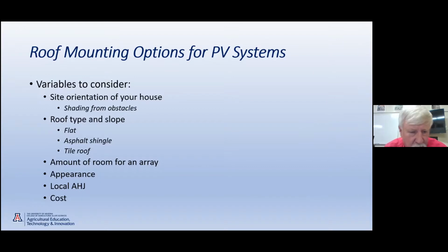Ones I didn't show in this picture, and I wasn't able to find, were any tile roofs. You certainly can have solar put up on a tile roof, but that would be something you want to consult with the installer, see what they're experienced with, because they use some different type of equipment. The amount of room for an array, you know, do you want to use the full amount of your roof, or are you only going to put up a little bit because it depends on your budget?